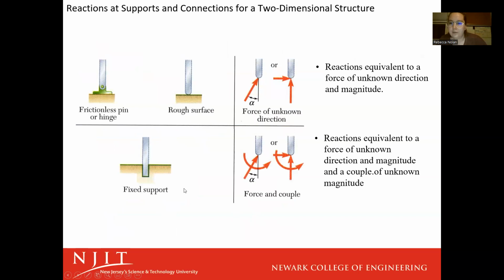Any questions on that? The last one is the fixed support. So picture when you see beams in concrete or anything like that, you're going to have a rotational constraint as well, because this area down here can't rotate, right? So that's our third one there.